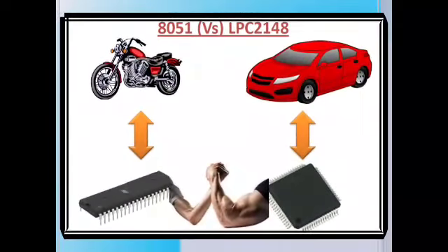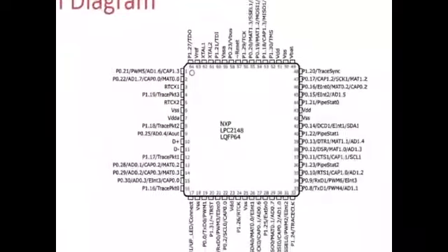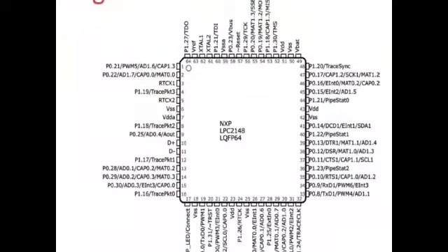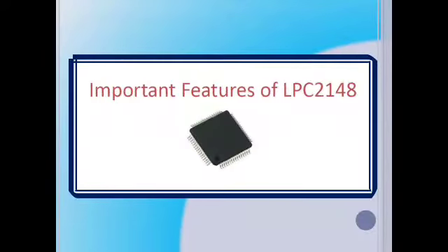The difference between a common 8051 and LPC2148 is simply given here. The 8051 is the core, but the additional features, such as the protected mode, you have in the LPC2148. This is the pin diagram of your LPC2148, and we can see the important features in detail.